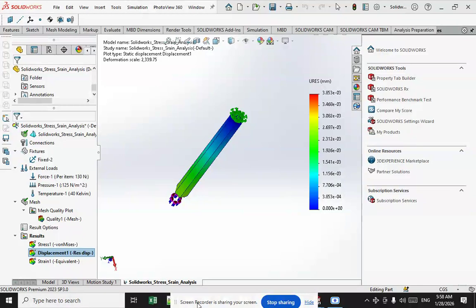Further, each member of the truss structure might then be treated as a unidimensional member with the forces acting along the axis of each member, in which case the differential equations reduce to a finite set of equations with finitely many unknowns.